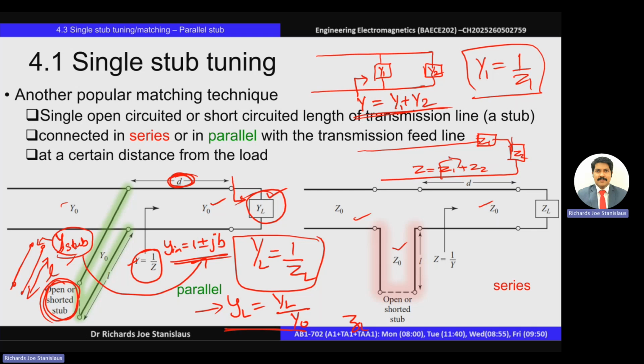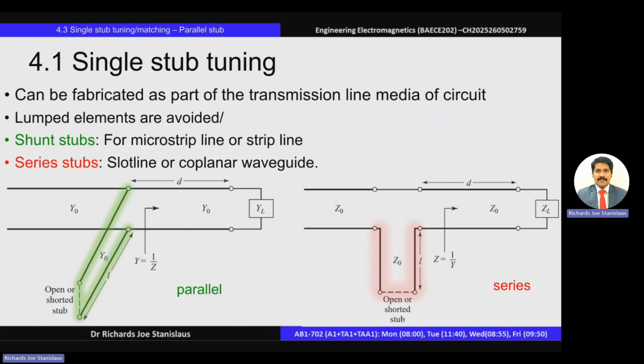So the susceptance needs to be cancelled out with the use of this stub. So you have an open circuit stub, where one end will be open circuited. The admittance that this stub contributes would effectively cancel out the susceptance available in the Yin, which has a real value, the conductance, of 1, right? We'll go through this in the slides so that you'll understand further.